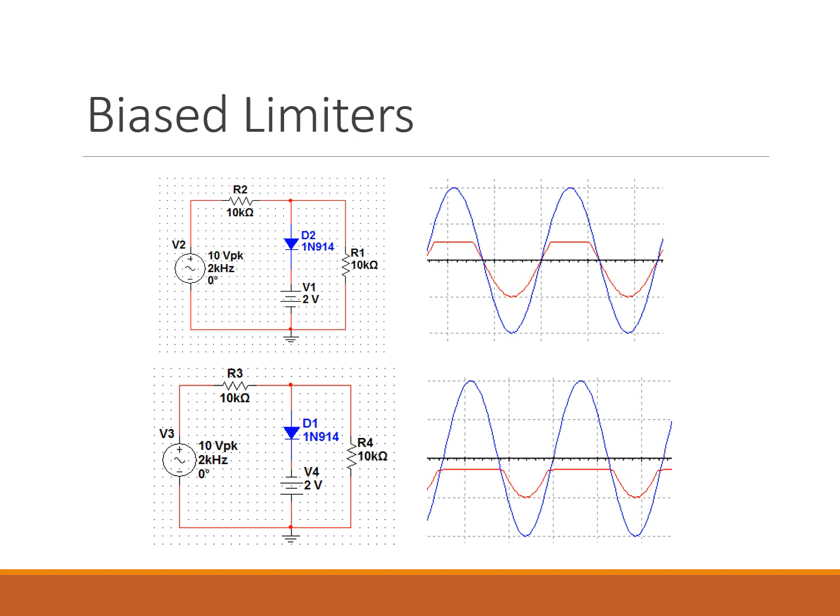On the negative half of the waveform, that just remains untouched because remember it's reverse bias and all the output is shown across there. So the output, what does it look like? Everything below 2.7 volts passes. Everything above that gets flattened.